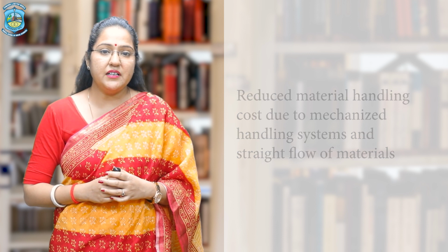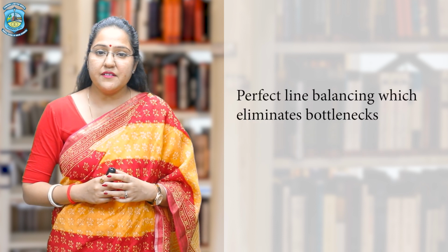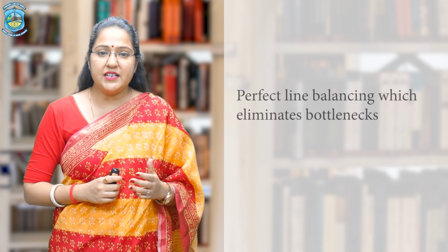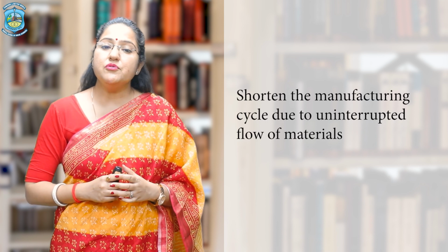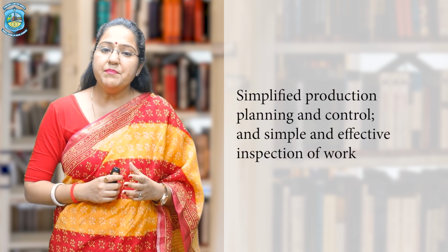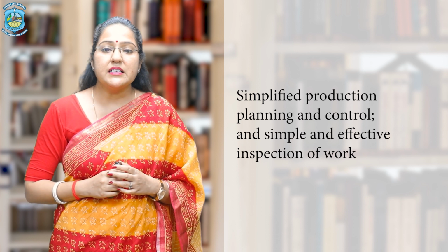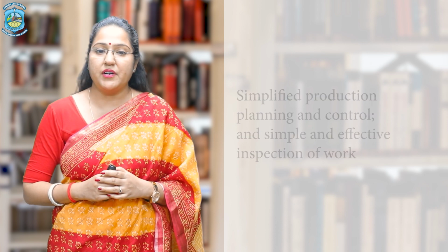The advantages of product layout are that it reduces material handling cost due to mechanized handling systems and straight flow of material. There is efficient space utilization. It gives perfect line balancing which eliminates bottlenecks. It shortens the manufacturing cycle due to uninterrupted flow of materials. It simplifies production planning and control, and it is simple and effective for inspection of work.